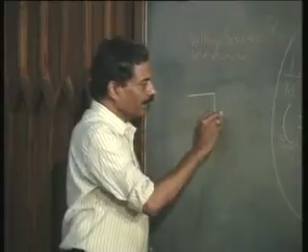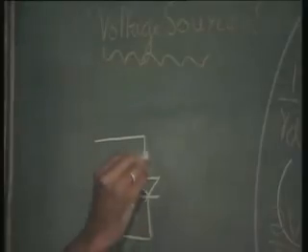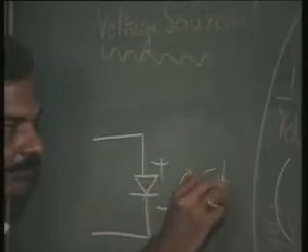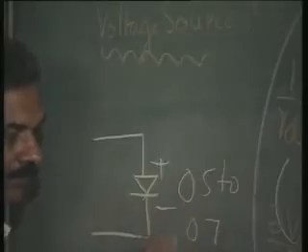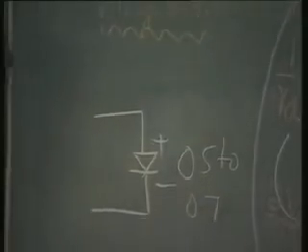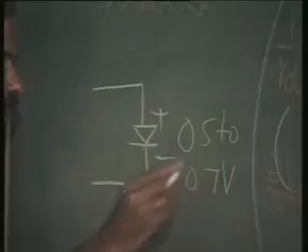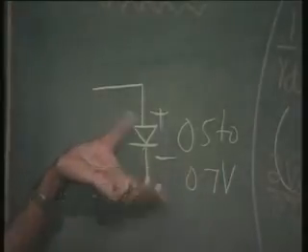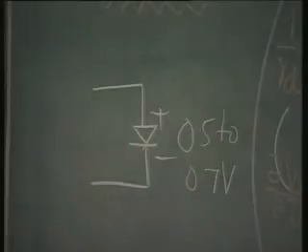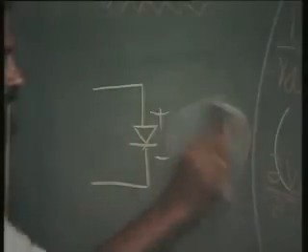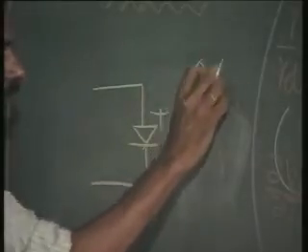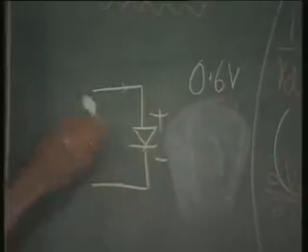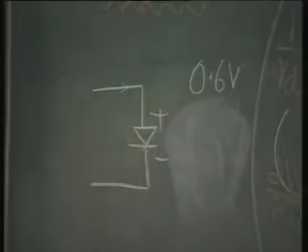Diode is forward biased, and we have already established that this forward bias voltage is around 0.5 to 0.7 for most of our small signal diode applications. We can take this. So, can't we therefore use it as a fixed voltage source with this drop? Let us say it is equal to 0.6 volts at a certain current, and it does not change much with respect to current, that we have seen.